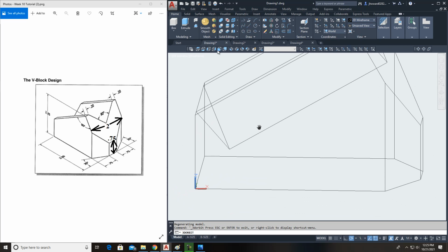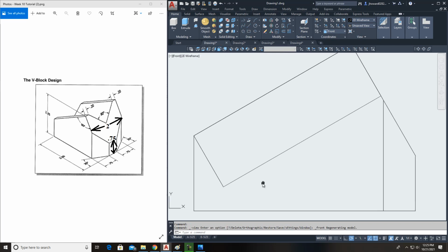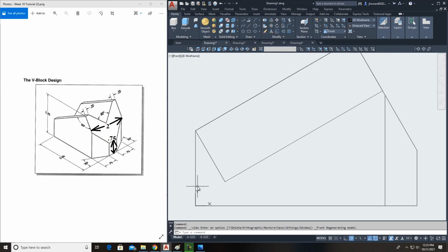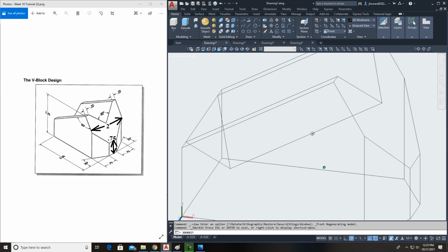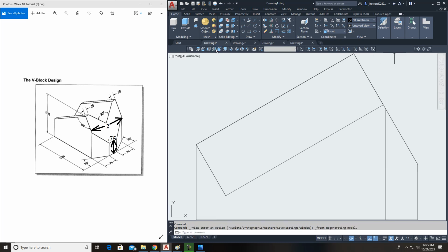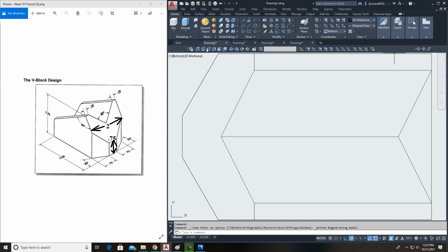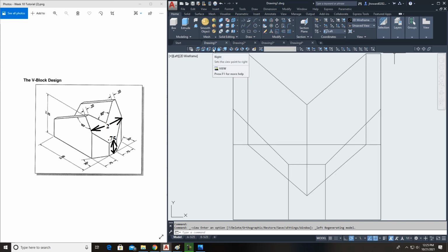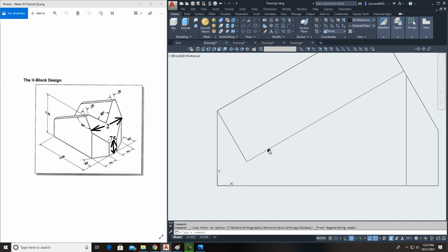Now you can also go to the side view of it just like that and see how it makes your XY plane fall on that. I'll take and turn it, and that's one of the beauties of this, if you do use these tools, you can go to the front, the bottom, whatever, and it'll always be on your XY plane. So I'll turn to that side, and then I have my XY. All I have to do is do an extension on it. Use extend, click to the line you want to extend to, and then click on that, and it will shoot that down for you. Okay?